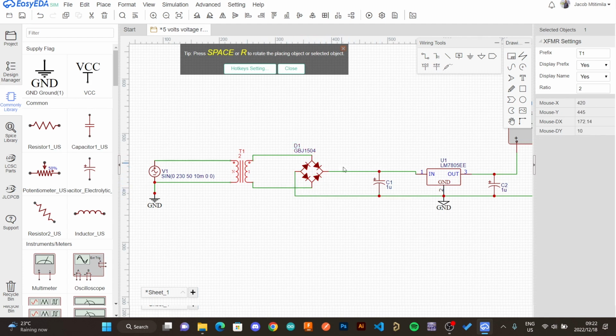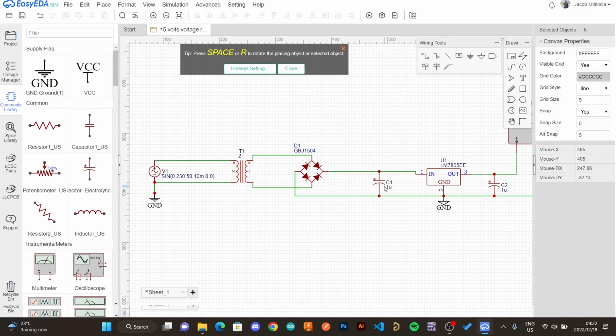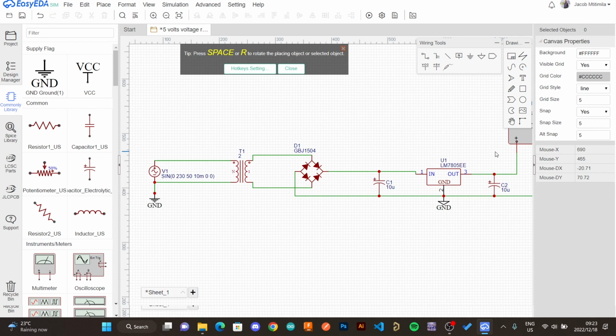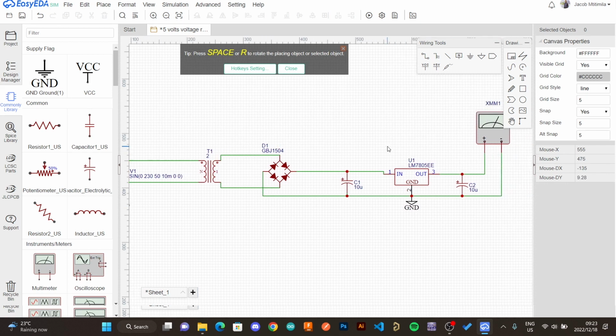less voltage to work with the diodes. And in here, you just need to check this one and just put 10 microfarads. So in order to put 10 microfarads, just double click the 1u and change to 10 microfarads. Click enter. So that's here. So these capacitors are good in every circuit to filter the voltage that you're working with.